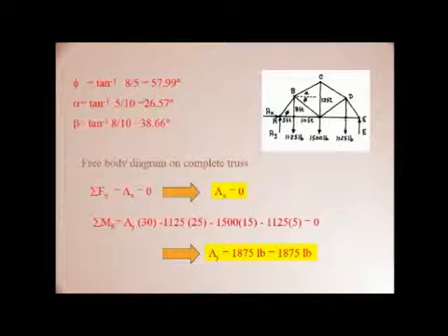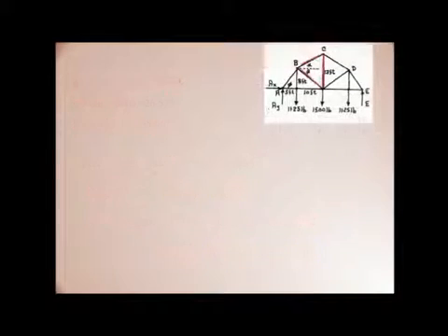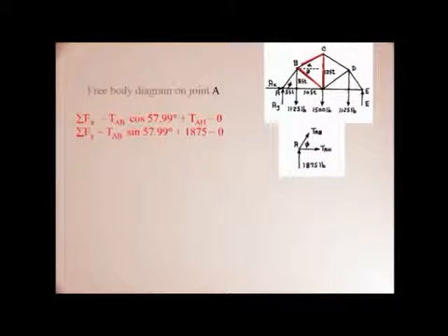That means summation of Fx equals 0, summation of Fy equals 0. Now similarly, by solving, you get Ax and Ay. Now draw the free body diagram of point A. Here three forces are acting: Ax, Ay and another tension AH. This is the figure. So by solving all these equations, these are just resolution of forces, solving them.